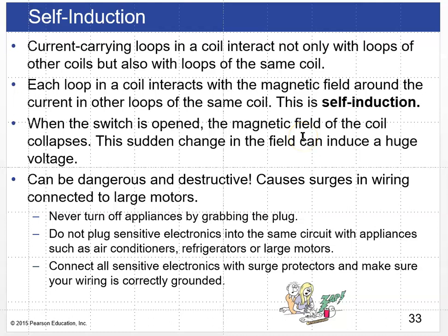You should never turn off appliances by grabbing the plug. If you notice a really large spark when you pull something out, like a refrigerator that's running, that's what you've done. You've interrupted the circuit, caused the magnetic field to collapse, and induced a huge voltage.